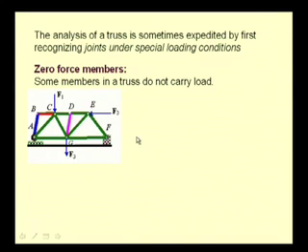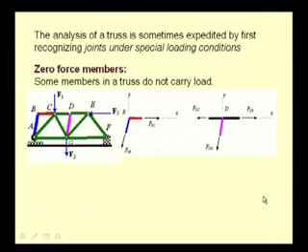and this picture depicts a truss element, that is A, B, C, D, E, F, connected by a roller at A and by a pin joint at F, and various externally applied loads like F1, F2, F3 at joints C, E and G. Let us consider the equilibrium of this joint at B. We have this force in the member BC, FBC.